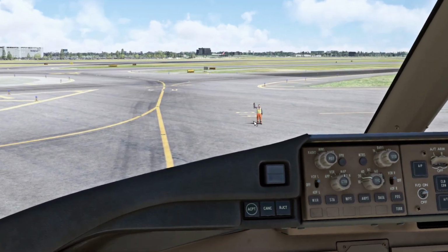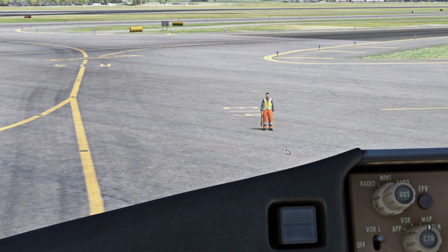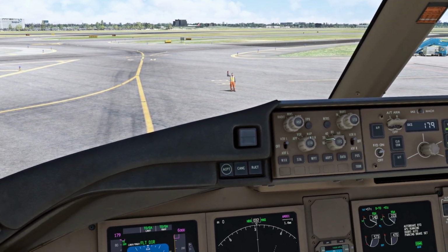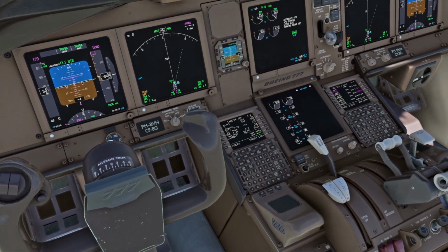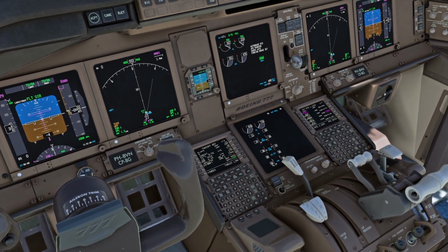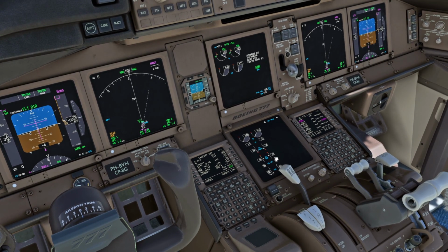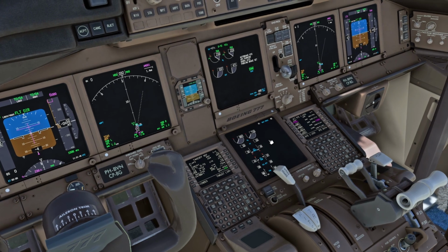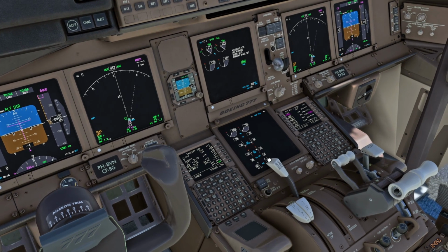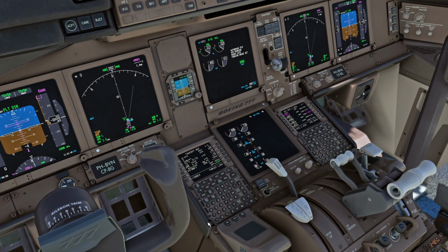Okay, the ground crew shows the bypass pin, so that's good. The marshaller, thank you for showing it. It shows that we can operate the nose gear ourselves right now, so we can actually steer the airplane on the ground. Again, the EGT red line is removed and the engine stabilizes, so we have successfully started the engines.